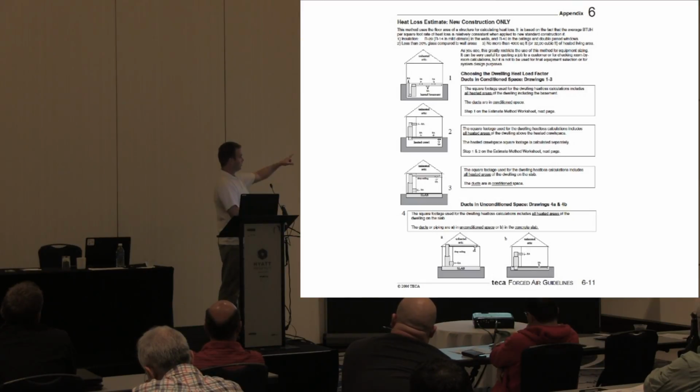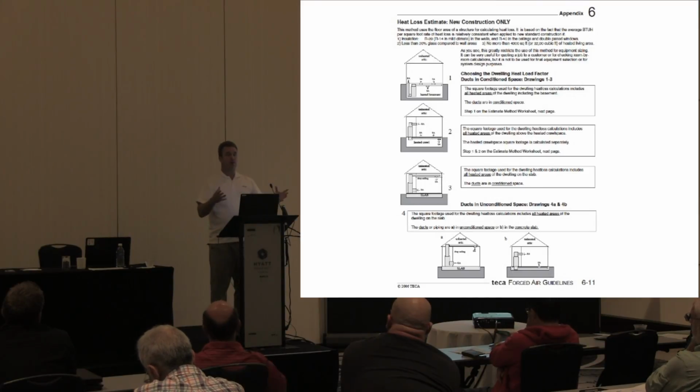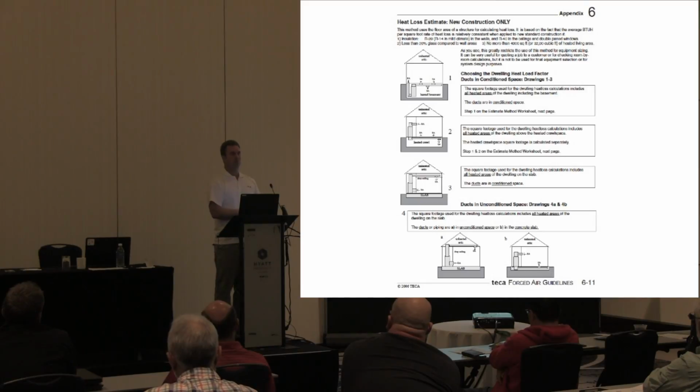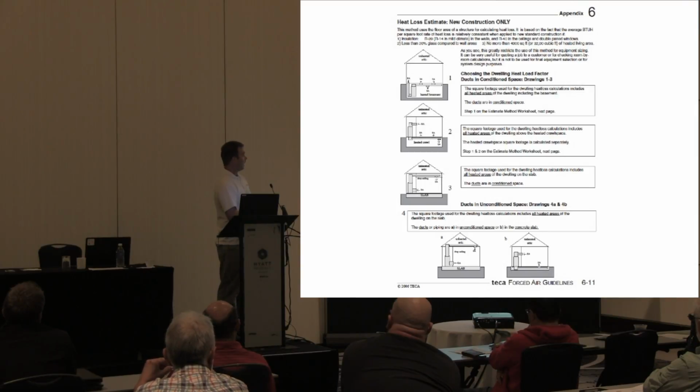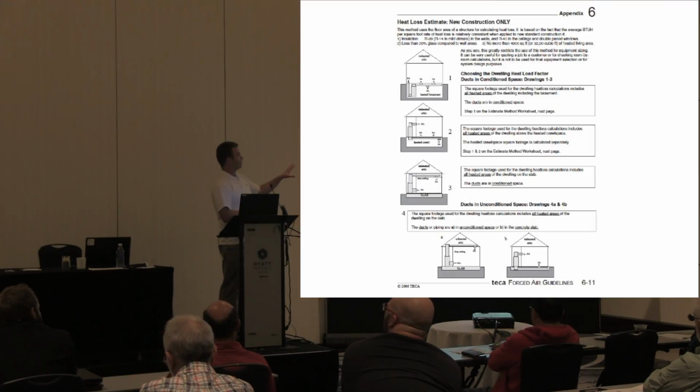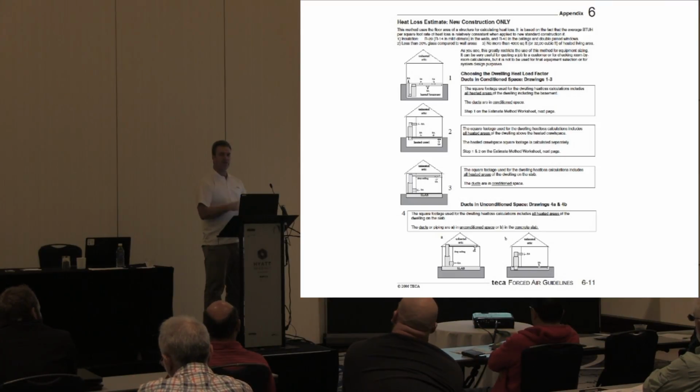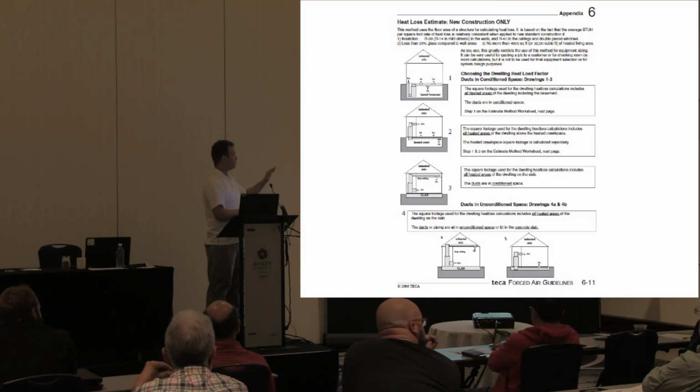No, yeah. And then R40 in the ceiling, double pane windows, and less than 20% glass compared to the wall square footage. So a standard subdivision house. Not one sitting on the side of a hill with solid glass across one wall. This will not work. And it's not bigger than about 4,000 square feet. So it'll restrict a lot of things for you, but if you guys are building a lot of those kind of size houses, it gives you a quick kind of thing.